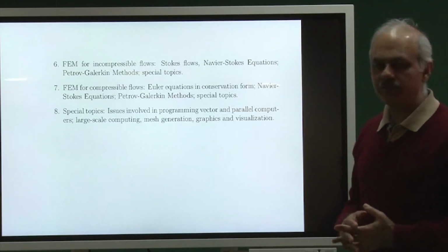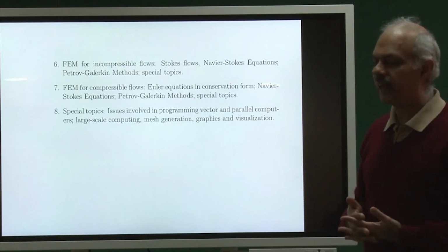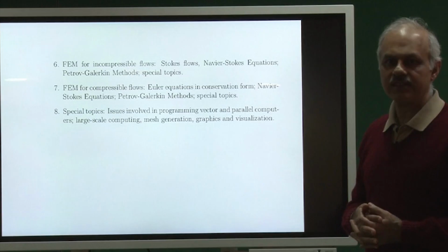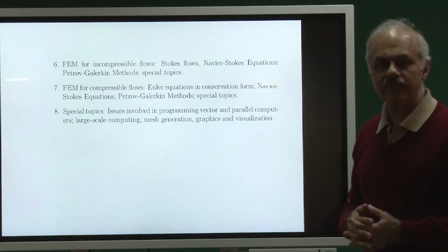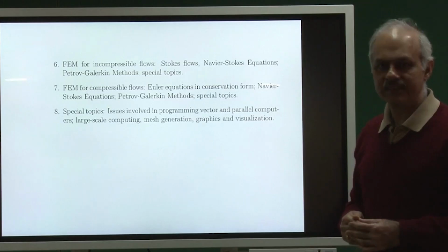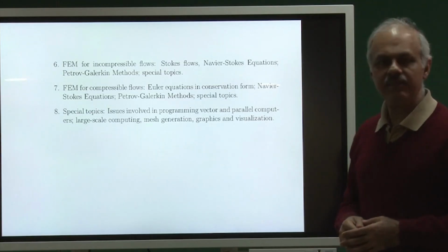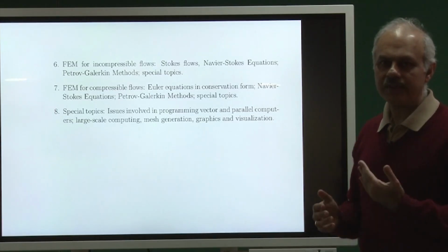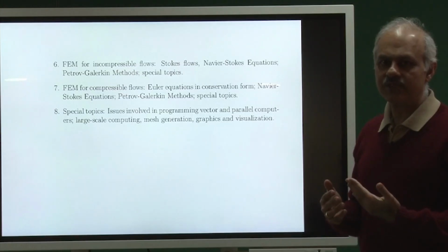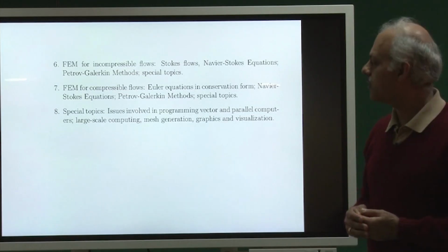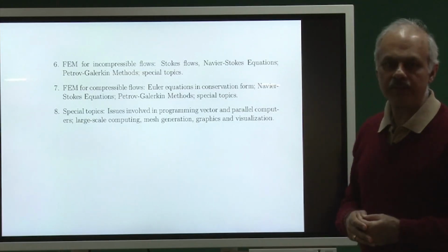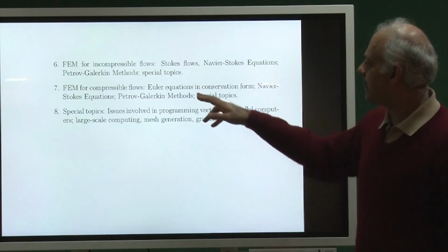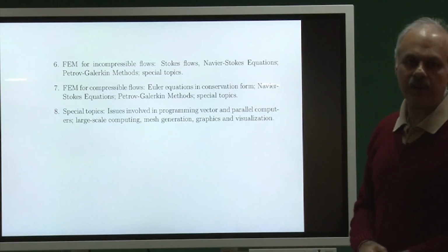Having done that, we will move over to some very preliminary issues with compressible flows. Compressible flows have their own challenges, for example shocks. How do you deal with representing shocks? Most of the time we would be using continuous functions, but at least in an inviscid framework, shocks lead to discontinuous solutions. So how do you represent discontinuous solutions using continuous variables, and what kind of problems does it pose? How do you capture shocks? Those are some of the challenges we will try to address in this part of the course.